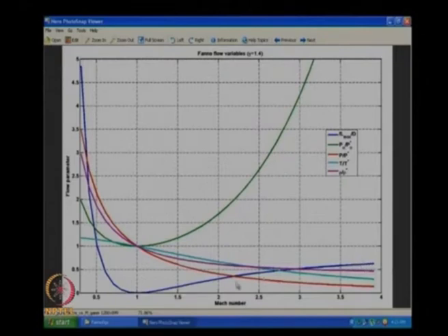Okay. And when I go closer to M equal to 1, when I go from Mach 2 to Mach 1, it needs only roughly 0.3 meters, if I assume the same f by D. While in this case, for the same length, it would have gone from roughly 0.65 or 0.7 to 1. Yeah, that is what you are seeing here. It says that subsonic flow can handle a lot more length of the tube before it reaches Mach 1, while supersonic flow cannot. Okay, important statement there.